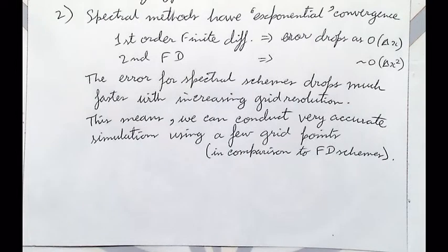And for this reason, the spectral methods are the method of choice when people study turbulence. I will discuss turbulence in some detail over the last two classes, but if you remember, turbulence involves a large separation of scales. Things might be happening at very large scales, but energy eventually gets dissipated, destroyed at very small scales.